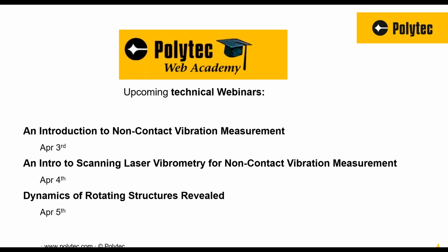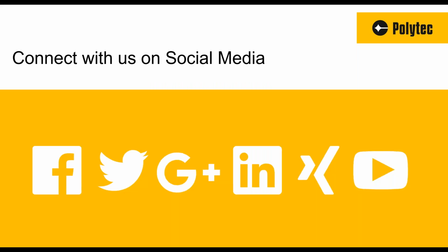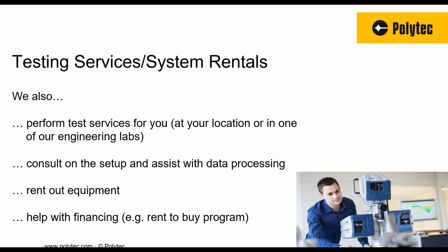Last question here is, how can we eliminate background vibration when measuring at low frequencies, like picometer levels? Yeah, that's a good question also. Background vibration, it's important to eliminate that, especially if you're measuring in that range. So, of course, we're able to measure down to picometer, but background vibrations can be at that level or even higher, nanometer level, especially for ambient vibration, say less than 100 hertz. So people walking around in your building,